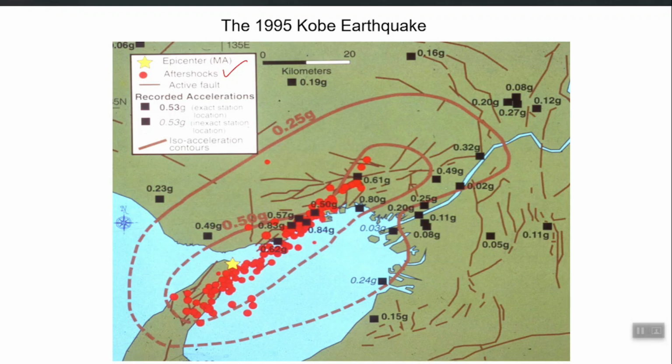After a certain earthquake, we can also have readings of PGA at different locations for that particular earthquake, and we can draw a map of the PGA values which were experienced during that earthquake. These kinds of maps are called intensity maps, because they tell us what the intensity of that earthquake was in the past, right?